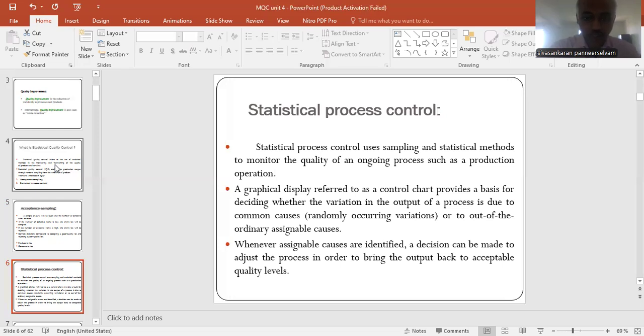After recording the existing process of the given production operation and making it a graphical display by means of control charts, say X bar and R chart, which is one of the primary tools in variable charts, we can claim, using those control charts, whether the proposed manufacturing model behaves within the safe control limit or not.